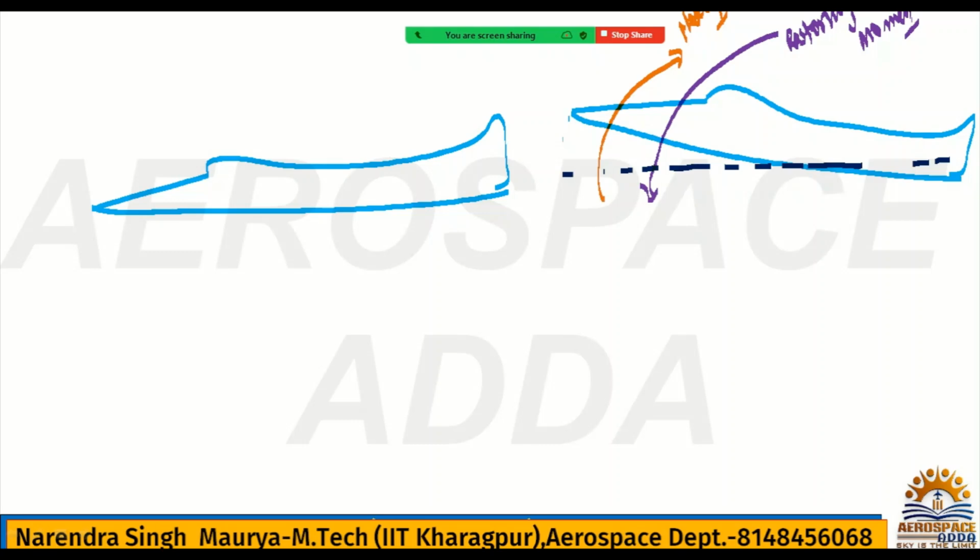Okay, so the moment acting increases the angle of attack, and because of that, it is approaching instability. It is going to make the aircraft unstable. Why? Because as the angle of attack keeps increasing, at last it goes beyond the limit, the flow separates from the surface of the wing, and then loss of lift happens.